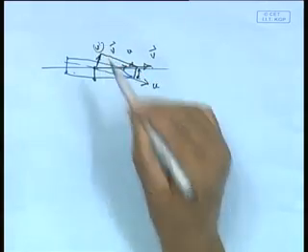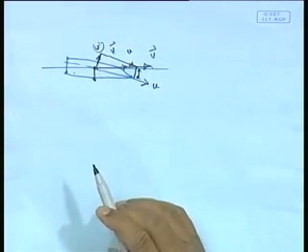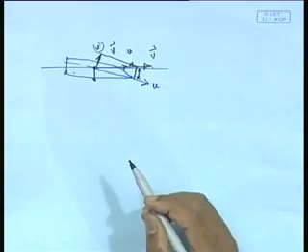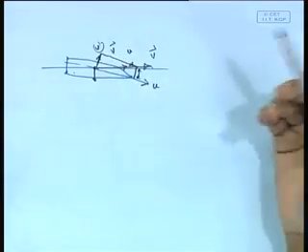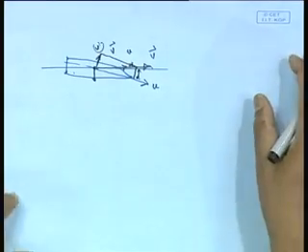So I have a small v created, sway velocity, and I want to know that sway velocity must come to 0, because only then will u and vector v align themselves to each other. So these are the kind of questions I am asking, and these are the answers I am trying to find out. And if I want to do that, as I repeatedly said, I will come to the expressions, the basic coordinate system; we need to understand and write the equation of motion.